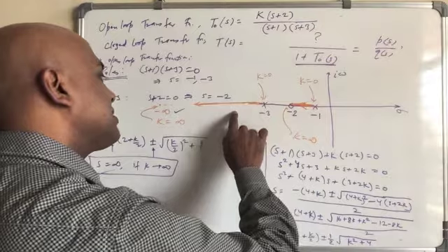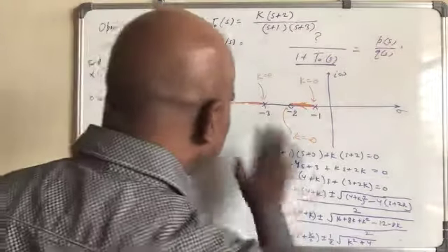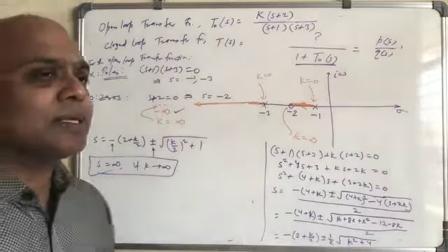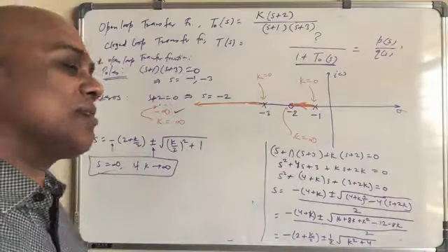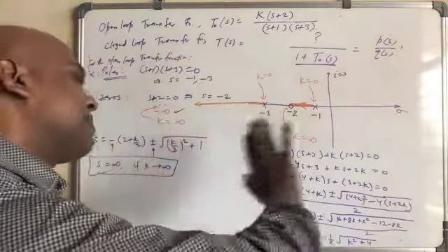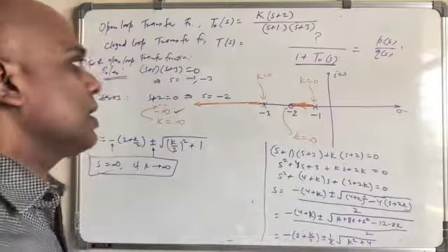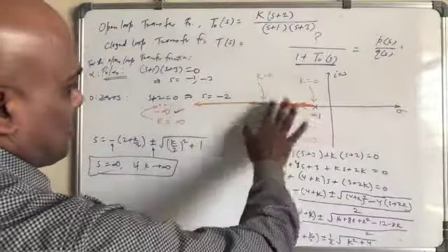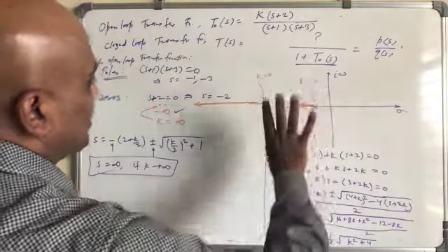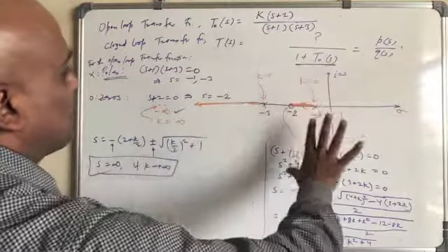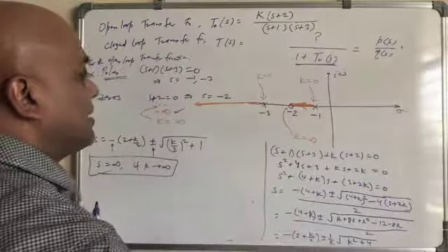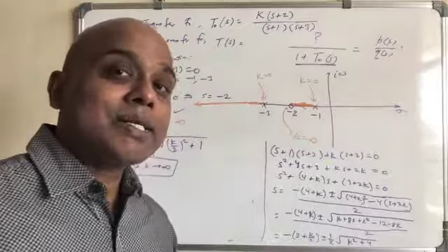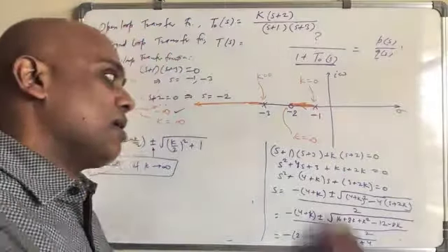If there is no zero, it will go to infinity. This is also because of many things, as I said earlier, that we have to look at from different perspectives. We will take one more example based on complex roots, see how to work it out, and then we will go to the general strategy you need to plot the root locus.